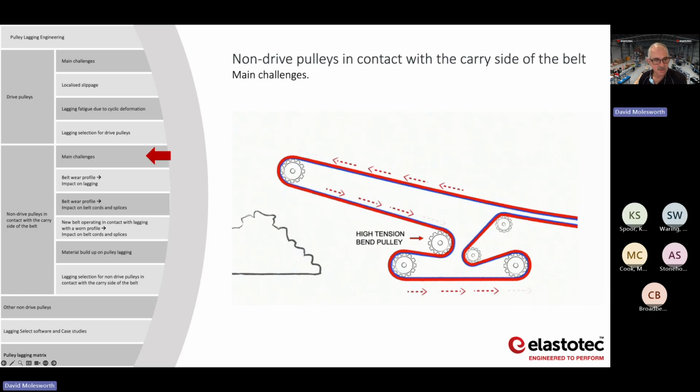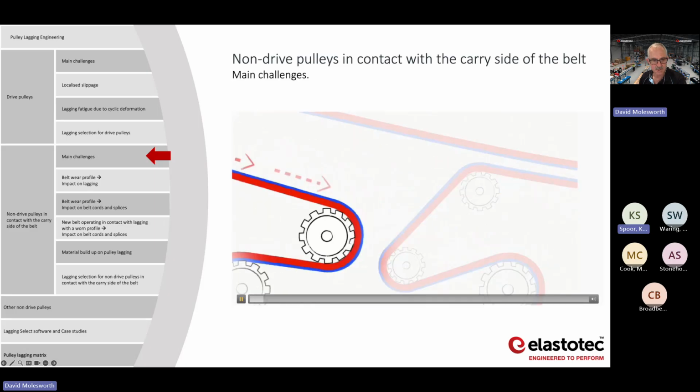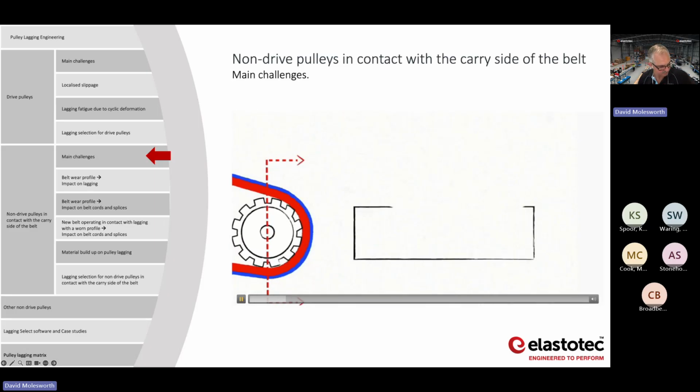So non-drives, we're going to look at the main challenges, and we're going to focus on the pulleys that are in contact with the dirty side of the belt, because these are the most demanding ones in terms of what happens with the lagging.